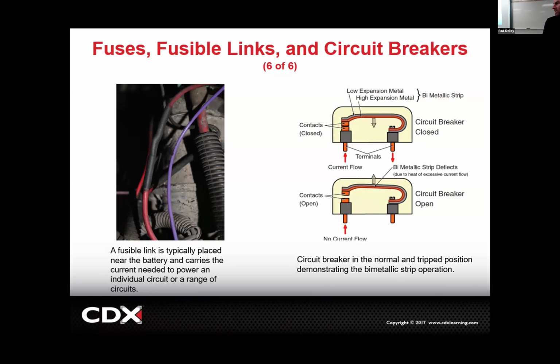So yeah, that'd be a quick, easy way to test it. You can see electrically it's hard to test it because there's no exposed wire. What I don't want you to do is make a nick right here. Don't cut the insulation off so that you can test it, because now you just sacrifice the integrity of the insulation. Makes sense? So it's better to actually tug on it. That's a good way to test those.